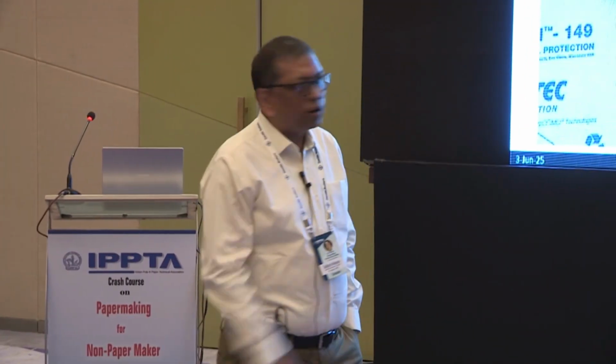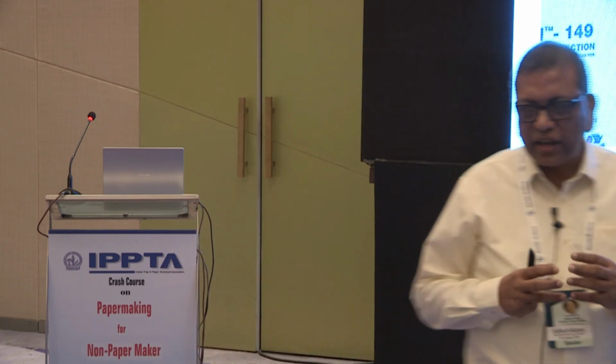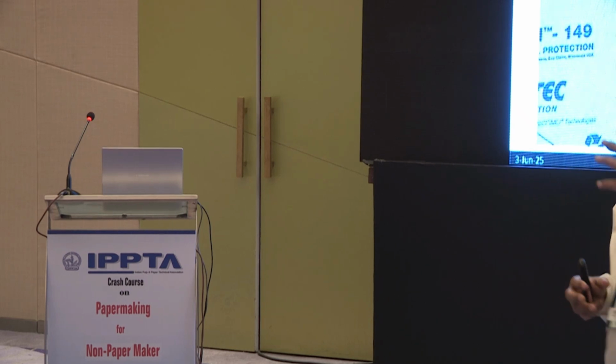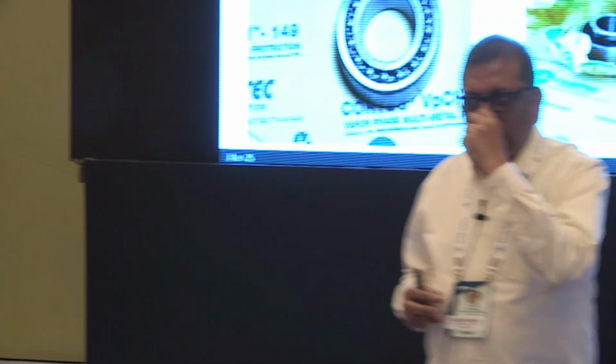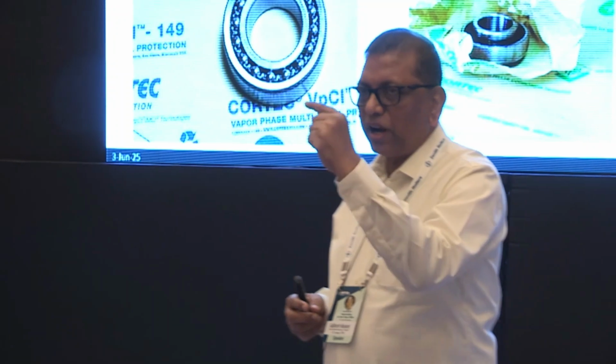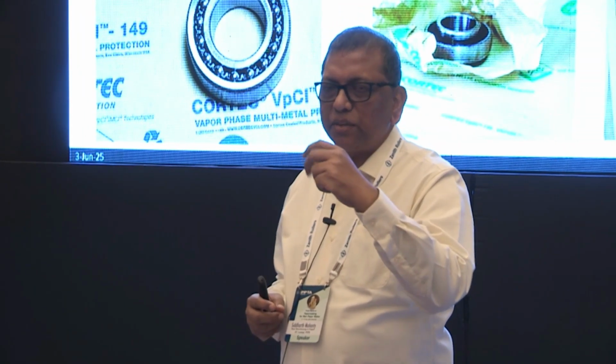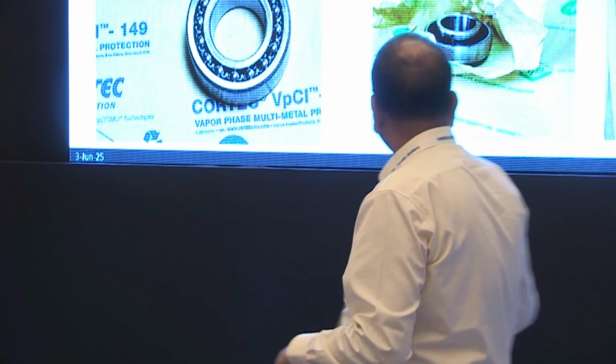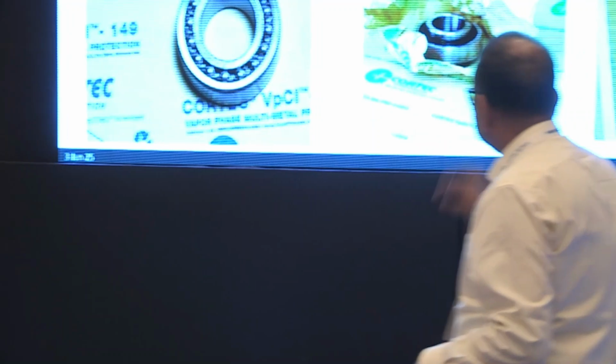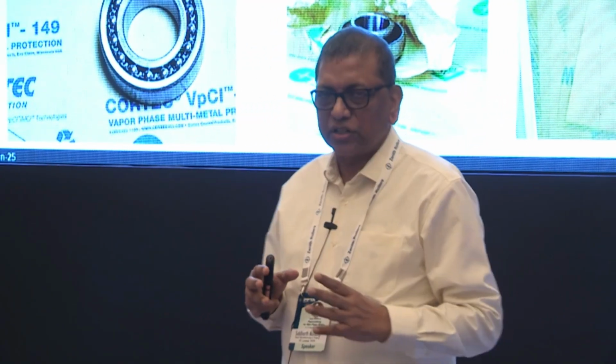Yeah. So, this is the VCI paper. There is a coating given on the paper, the metal is there, and there is a polar ion. That ion will react with the molecules in the coating, and in the presence of oxygen, the vapor will start coming out. The vapor will coat the top of the bearing or any parts you are wrapping. It will prevent the corrosion.